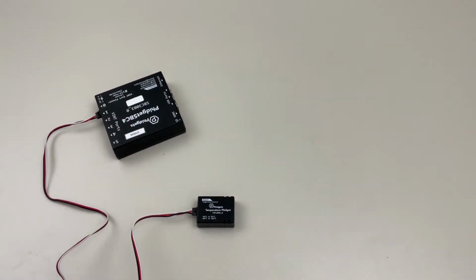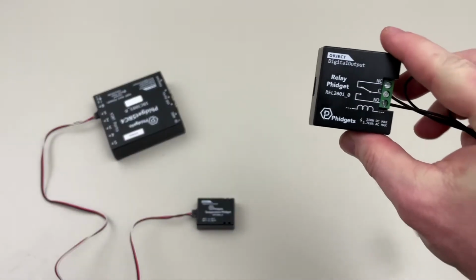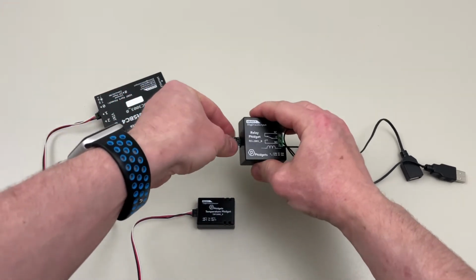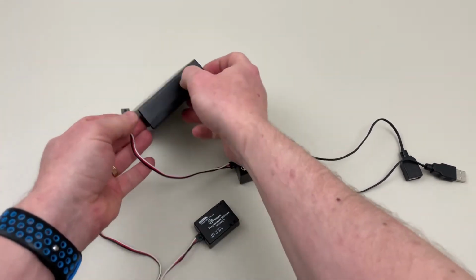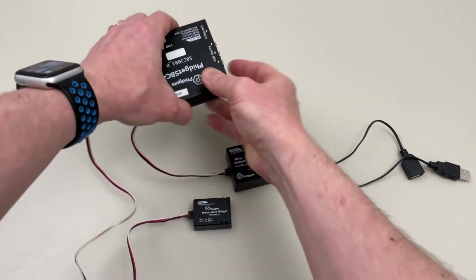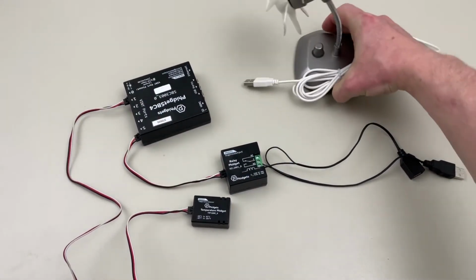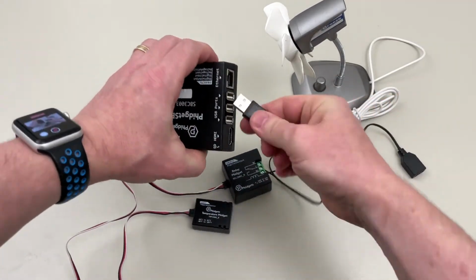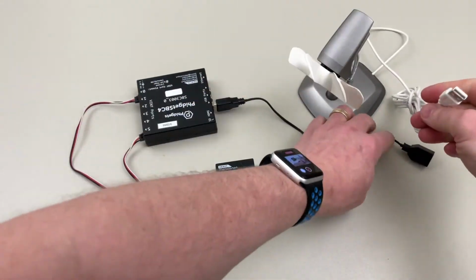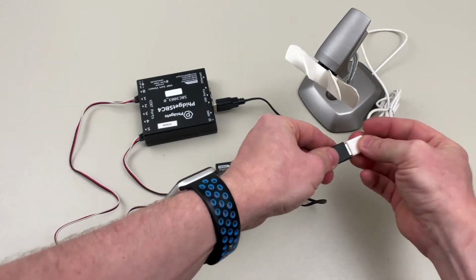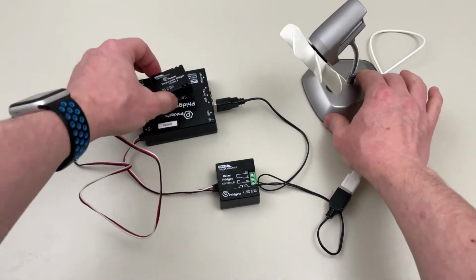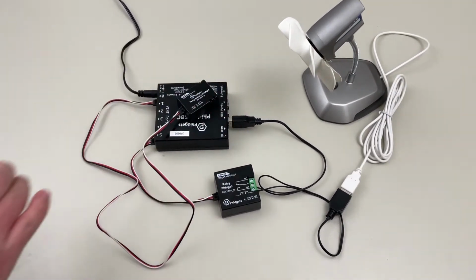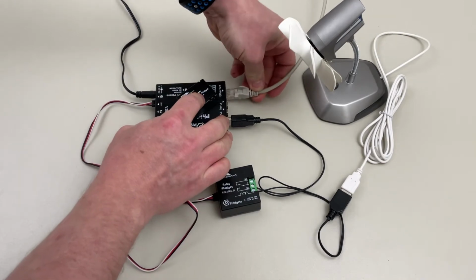I also want to be able to turn a ventilator on to cool the server down when it gets too hot. So I will use a relay Phidget and connect it to the port number 5. I will use a small USB fan for this demo, but I can easily switch any other electrical device with the relay as well. Now I can just plug the power and Ethernet cable in, and I'm ready to set up the software side of the solution.